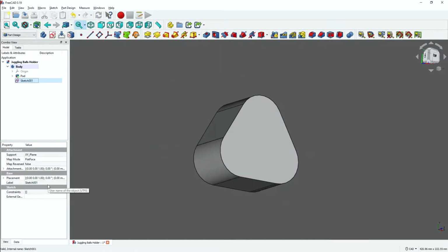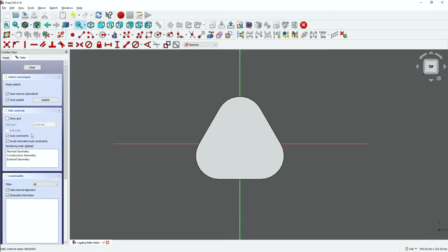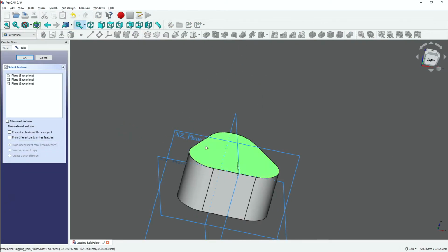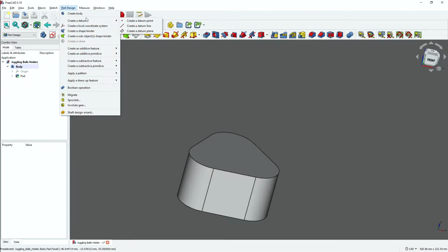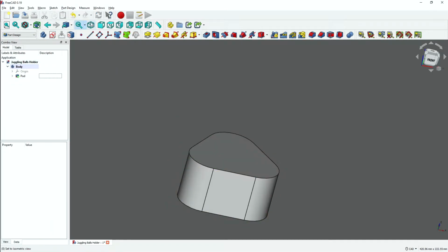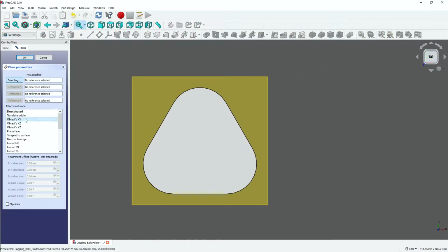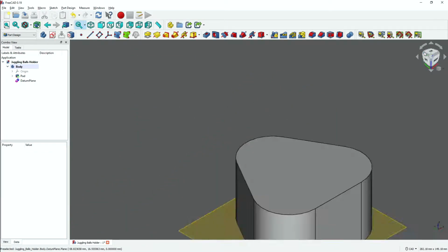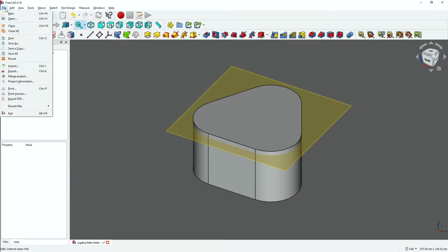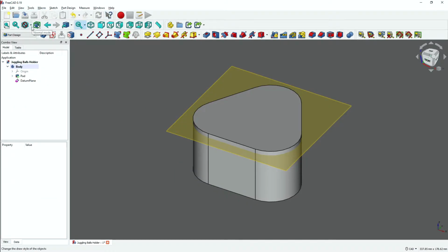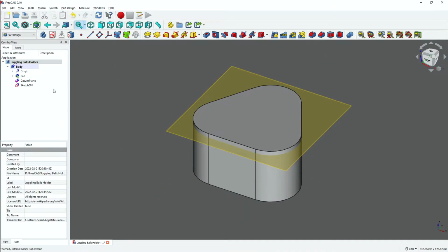So there is a problem within FreeCAD that's well documented. I think the name is the topological naming issue or something of that nature. And so when you create a new sketch, you don't want to do it onto a face. And while this is not a tutorial, in a previous video I made, which was also not a tutorial, I did that, and I did some more research, and I found that that's not the right practice for this software.